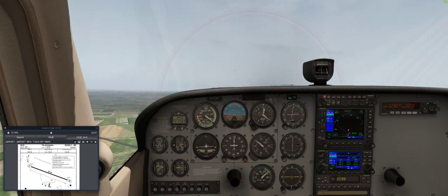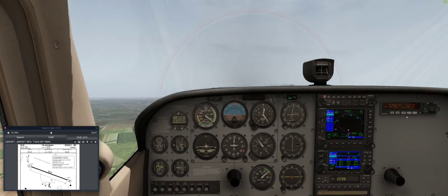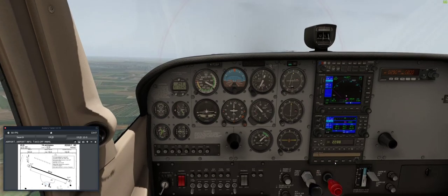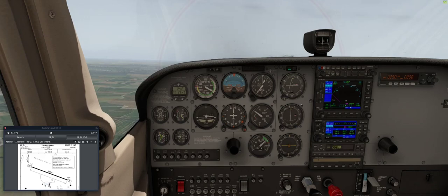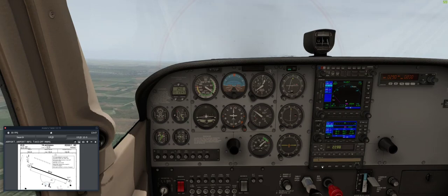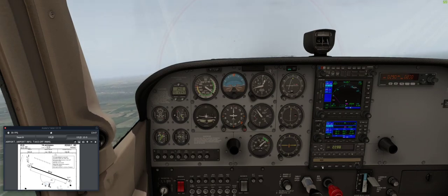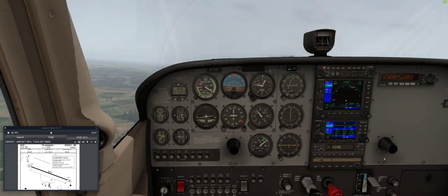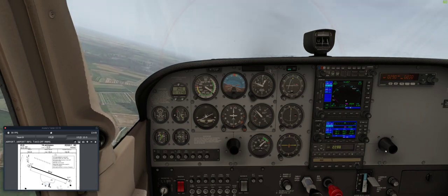So I've taken off, and we're high enough that it's safe enough to engage Autopilot, but what I'm doing right now is just trimming the aircraft so that it flies straight and it's climbing. We're in the GPS mode, so as soon as I turn on the Autopilot, it's going to turn left. I'm not going to touch anything. We need to hit this nav button not once but twice. Watch what happens. Nav lights, but watch what happens when I press it again. This GPSS lights. That's the mode we want to be in because we're following a GPS waypoint.